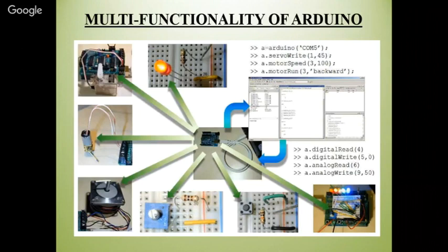The main important thing is the library, because when you get the library, the work is less. Some of the coding part is defined in the library. You need not write all the code, because in the 8051, when you code for the LCD, there are 2 to 3 pages of code. If you are using the library in the Arduino, there is half a page of code. So it is easy, but there are some negative points of the Arduino also.